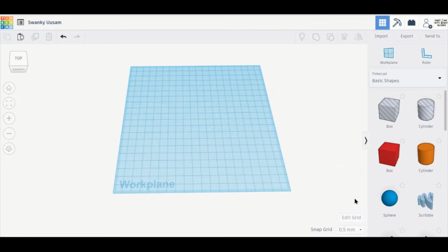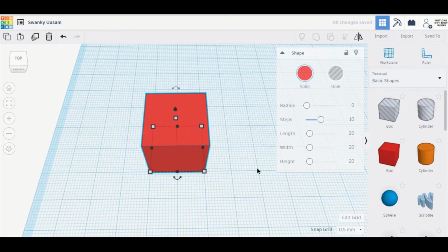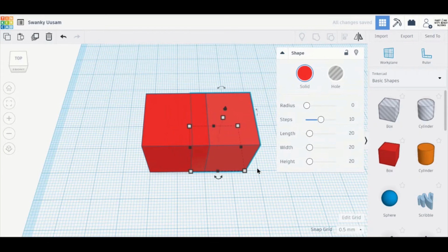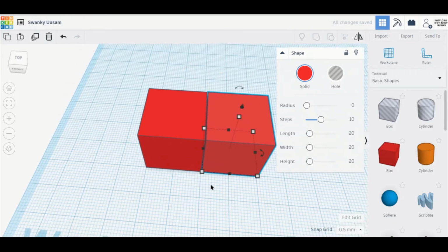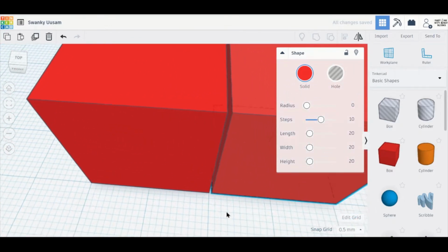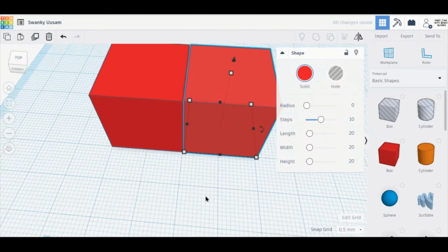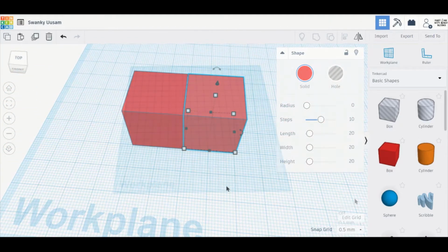When something is 3D printed, there's something called tolerance. This means that since the 3D printer has filament that it extrudes that isn't a perfect size, you have to give some space in the model for imperfections when you print. Since we're making a model that is meant to fit together, we have to be careful with tolerances to make sure everything slides together well.